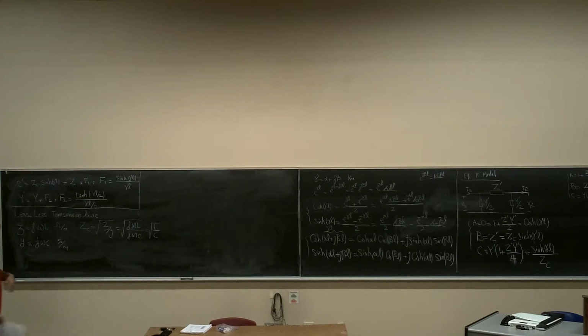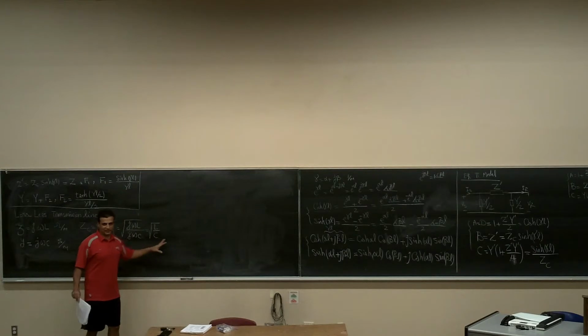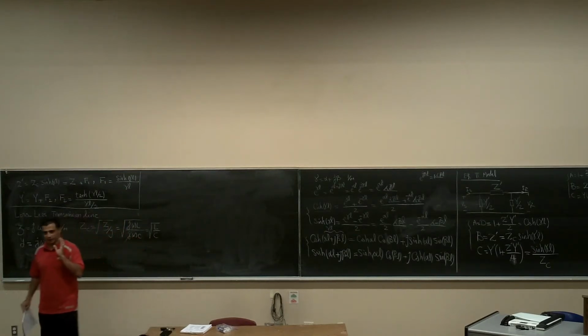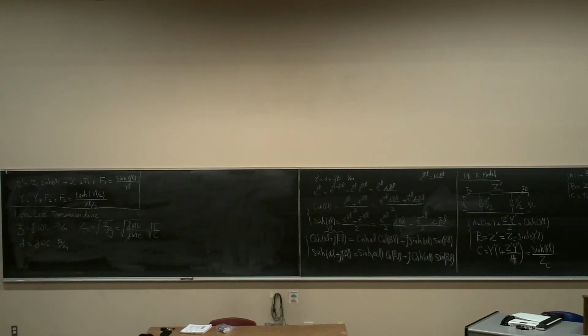We'll see a little bit further down that if the load is equal to this impedance, ZC, there is a very interesting thing. We're going to get there in maybe 10 minutes or so. But we have a lossless transmission line, R and G are 0, and the characteristic impedance, which in this case they call surge impedance, is just an ohmic, purely R value, right? That's the first thing.